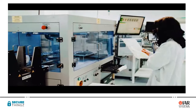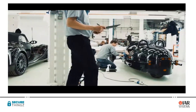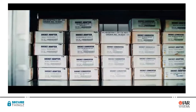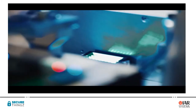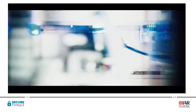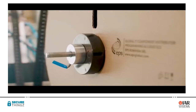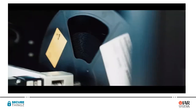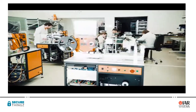We maintain a world-class quality level, compliant with all international quality control standards, including German automotive quality standards. We support all programmable package types at any volumes, including multi-chip packages with long cycle times, such as eMMC and UFS. 3D coplanarity checks are completed on all devices to solve handling problems on high pin count devices. We also offer extensive tape and reel services and manufacture our own carrier tape for components of any shape to help our partners eliminate manual insertion cycles in their processes.